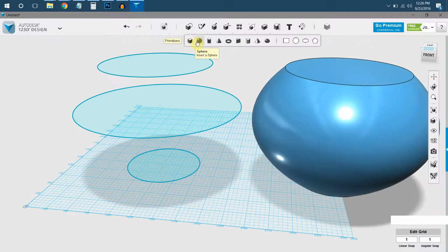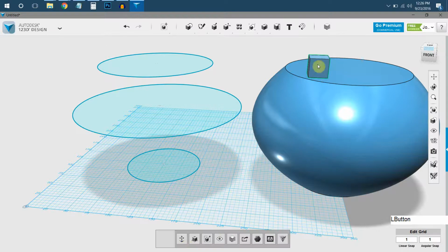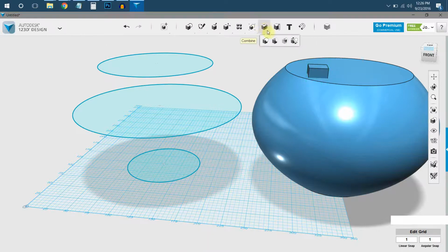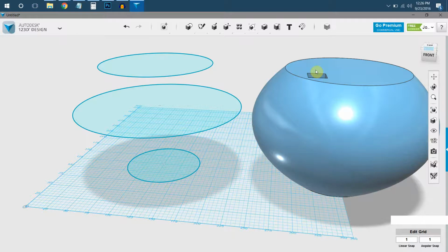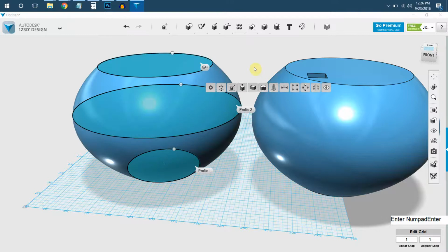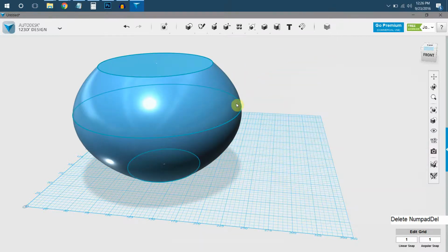up on this, like let's say you accidentally, and I'll show how I do this in a later step, let's say you accidentally cut a box out of this one here. Oh crap! Now I've got to go back and redo the whole thing. The nice thing about keeping your sketches in the scene is you can just go, oh, I'll just make a new one, and then go to Loft, and hit Enter. Or sorry, it's left click, not Enter, and then you can delete the original.